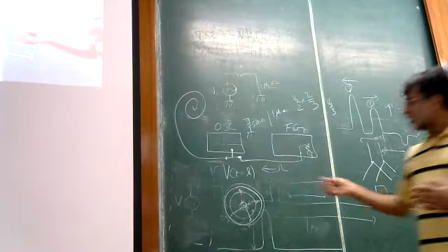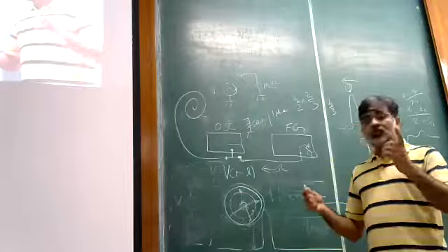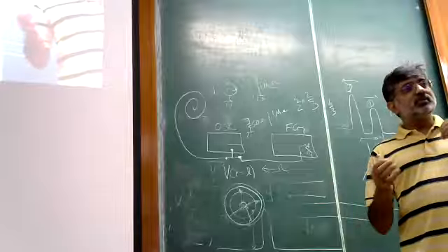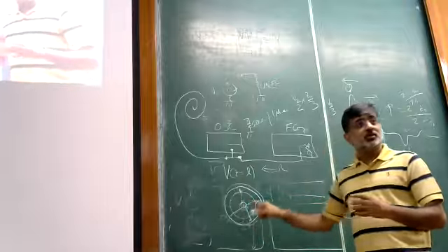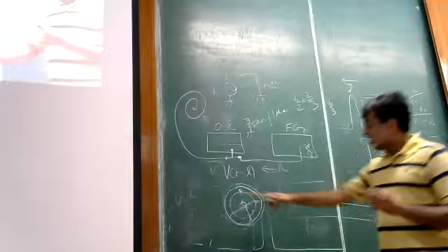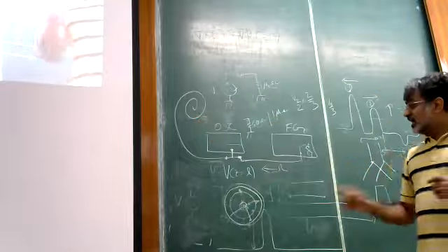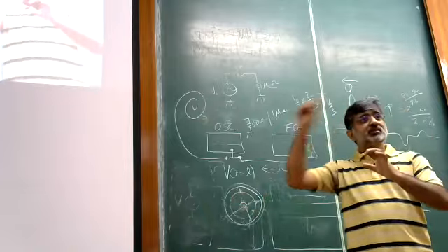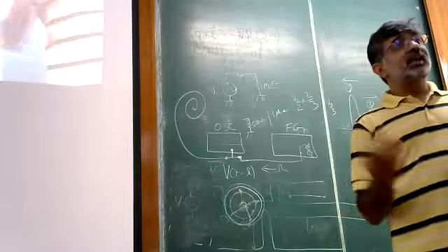So what do I mean by that? At some sufficiently high frequency, sorry, let me pause here for a second. What is considered small frequency or large frequency is basically related to the wavelength in comparison to the dimension of this cross section. We want the wavelength to be much larger than the cross-sectional dimension, not the length of the transmission line. Okay. That ensures that the overall cylinder doesn't allow you to fit one wavelength or half wavelength in that particular thing. Those will now give rise to transverse electric modes.